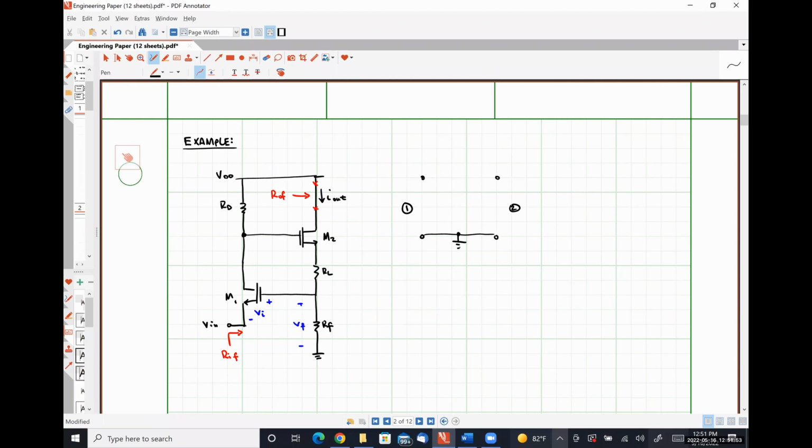Are we taking the output voltage, or the output current for this? This is a transconductance amplifier, so the output signal is that output current. The goal of this amplifier is to convert some input signal at the source of transistor M1 into some sort of drain current in transistor M2 that in turn drives some load, like a laser diode or something like that, where the intensity would increase as I out gets larger.